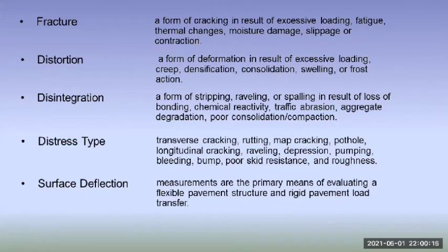Transverse cracking, rutting, map cracking, pothole, longitudinal cracking, raveling, depression, pumping, bleeding, bump, poor skid resistance, and roughness. Surface deflection measurements are the primary means of evaluating a flexible pavement structure and rigid pavement load transfer.